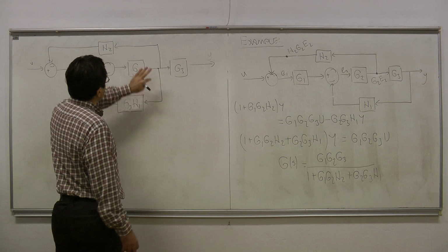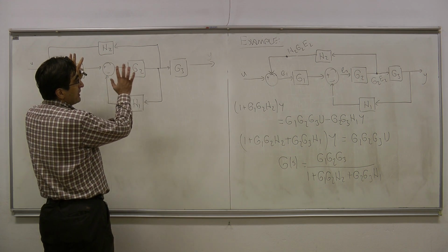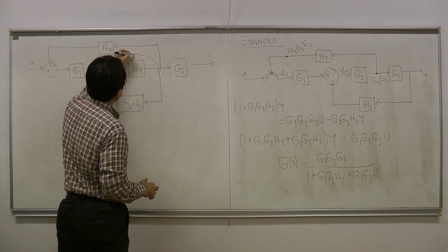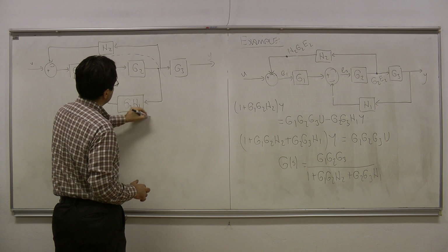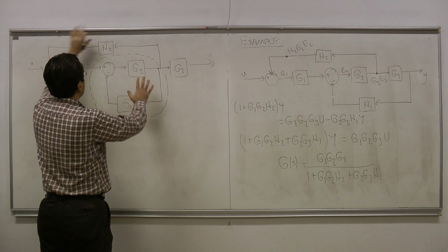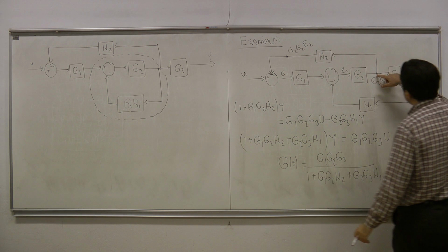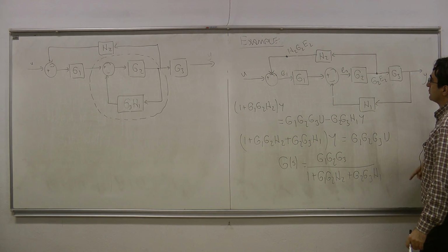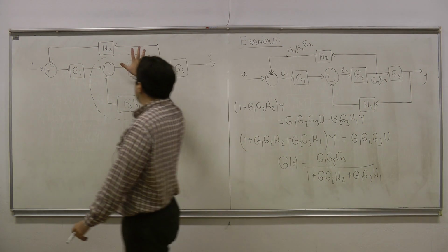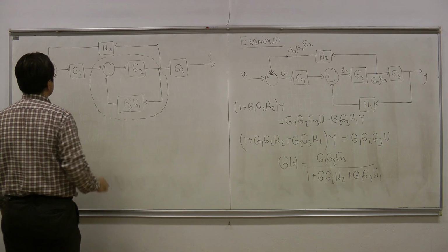So you see that when I make this modification, when I make sure that both of the systems are now the same, here there is a smaller feedback loop that you see here. Okay? So this is a smaller feedback loop inside a larger feedback loop. And we see that we really do not have any more branching outs in the middle of the feedback loop or summations in the middle of the feedback loop. Okay? Now I can actually apply my feedback rule to replace this small feedback loop with its equivalent.